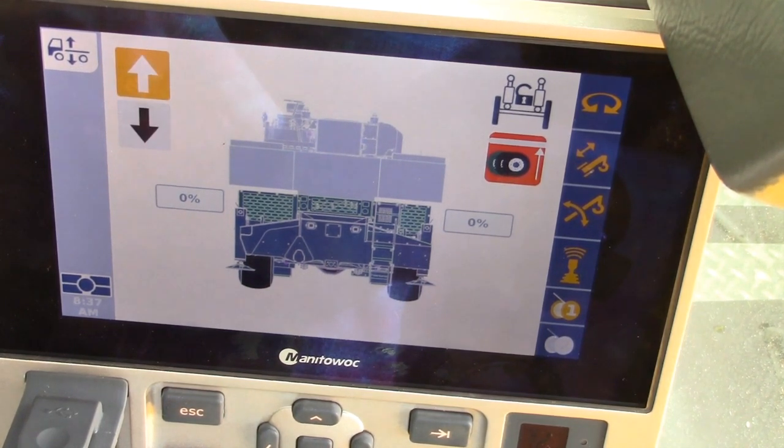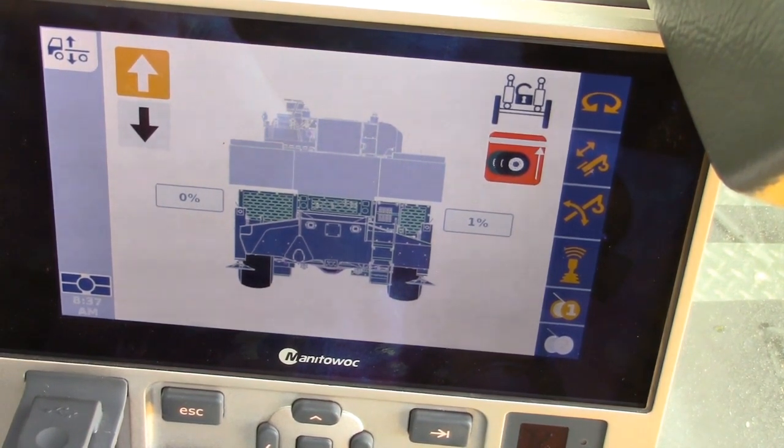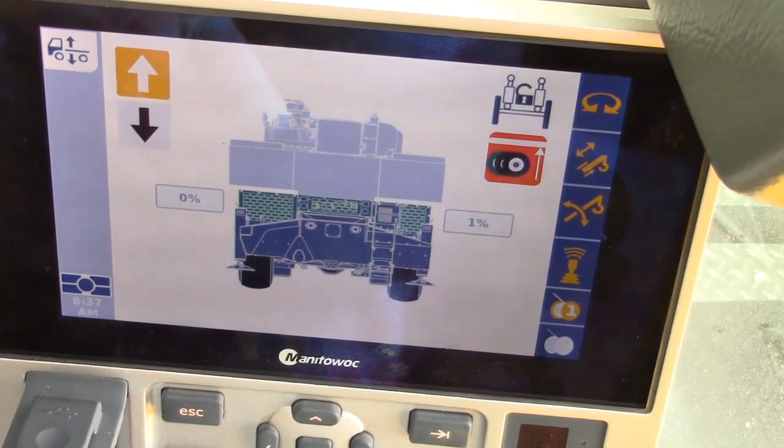When the crane arrives at the job site, it can be removed from the truck, and it is self-erecting. One notable thing is during self-erection there is a specific rigging code that allows the machine to install the boxes. This is an on-rubber code with no counterweight, and to properly run this code the suspension must be completely raised. This adds stability and stiffness to the rear oscillation and suspension circuit.